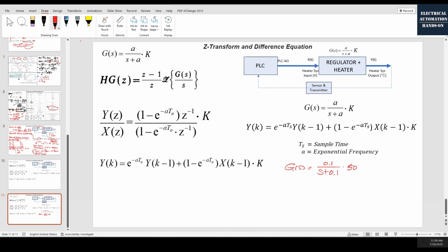In the meantime, when I determined this equation, the initial status, I call x0, was equal to 1 volt, and y0 was 50 degrees. That means based on the 1 volt control signal, once we regulate from 1 volt to 3 volts, the y will start from the 50 degrees and then follow a first-order style curve.